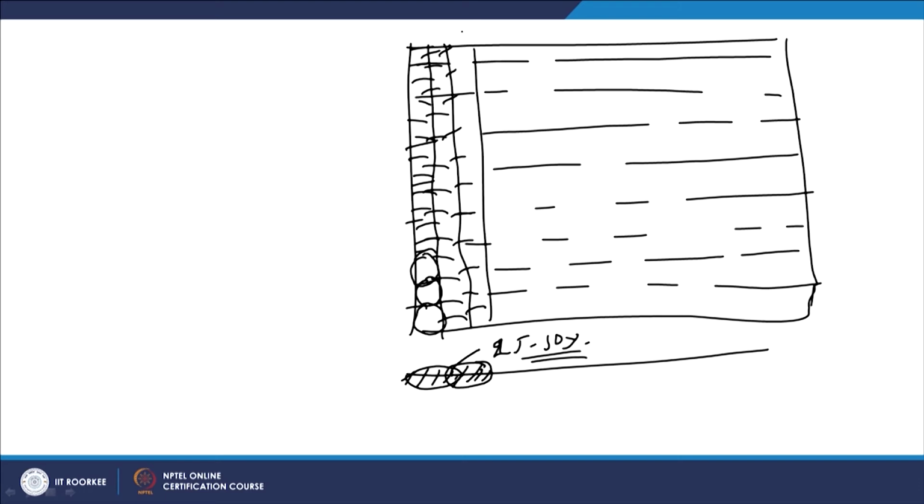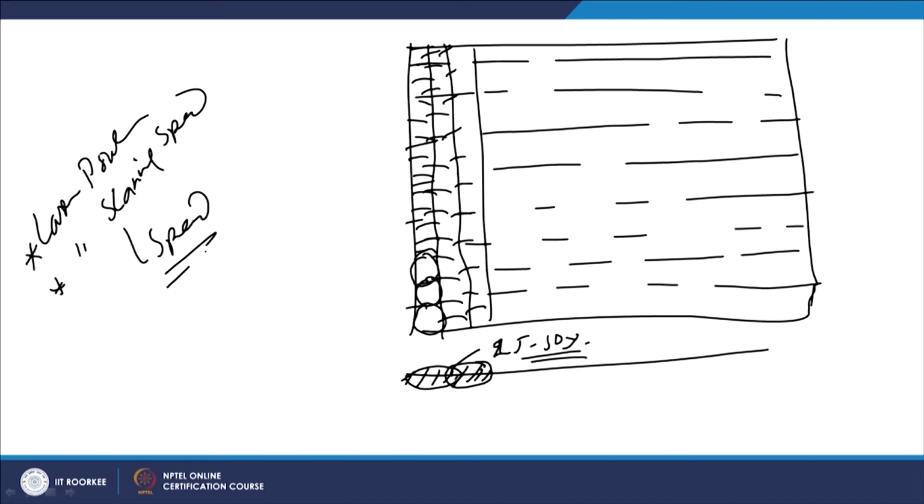As far as the parameters of the laser cladding are concerned, there are parameters like laser power and the laser scanning speed. So, this is the laser scanning speed, about the speed at which the beam is moved over the surface of the substrate, and the power is about the energy associated with the laser beam. So, how does it affect the quality of the claddings or the coatings which are being applied?